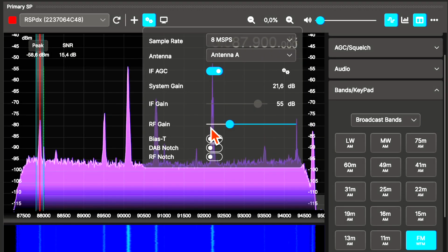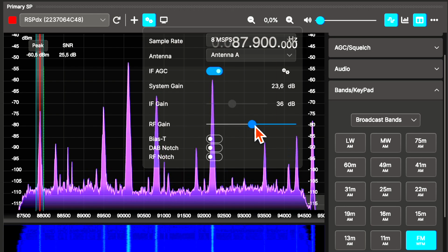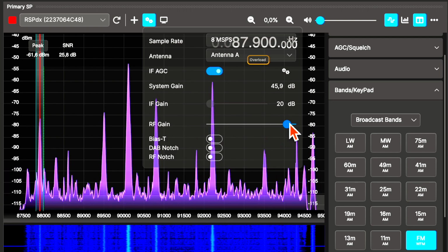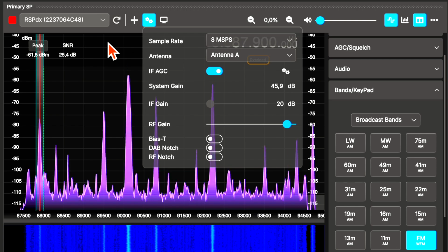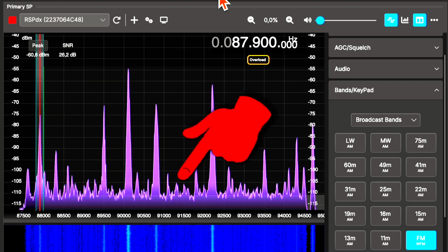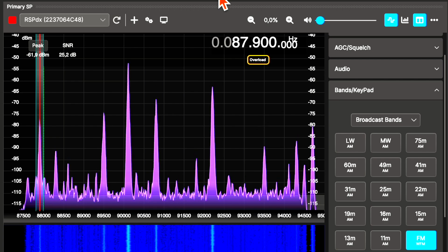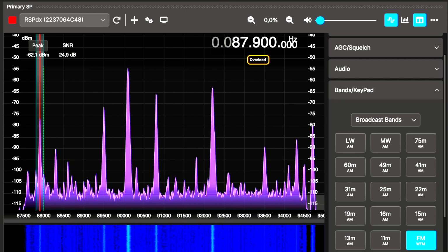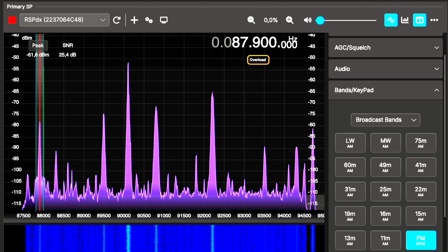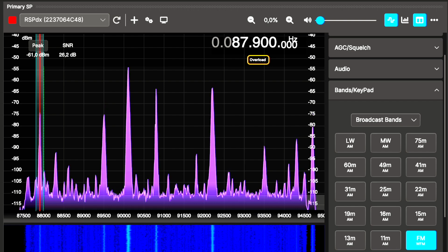We are turning up the RF gain to drive the preamp to its nonlinear range. The expected intermodulation products are actually superimposing the received signals. Within the FM band, intermods are a bit difficult to identify because we might confuse them with superimposed real signals. However, there is a suspicious indication that we will demonstrate in a few minutes. We don't want to get that far, but turning up the gain further, you might observe receiver blocking, pushing down practically all input signals.